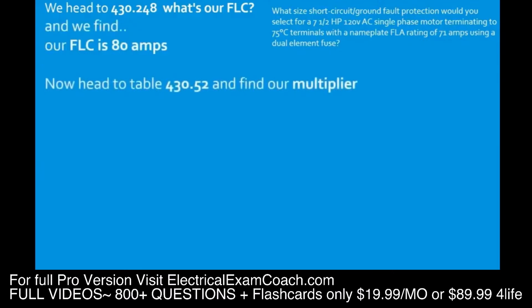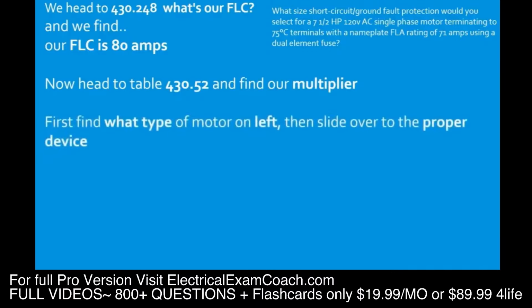Now we head to 430.52 and find our multiplier. Starting on the left-hand side and finding our motor, we come over and we tee off with our type of device. Then we're going to find that it's 175% for dual element fuses. Remember, this is just another demand factor.